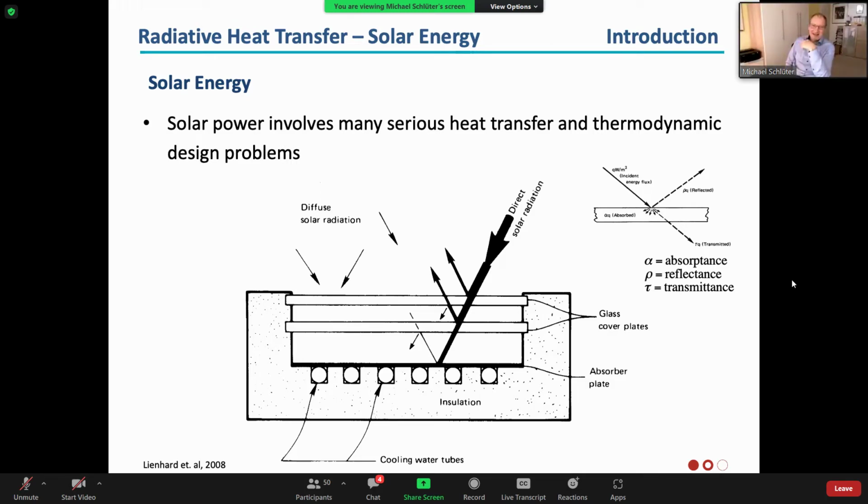You remember sunlight is reaching our Earth because the radiation works very well in vacuum. In space we have vacuum as well, so the radiation is not hindered by a vacuum, but the heat loss by convection is of course minimized by the vacuum, because if you have a vacuum, there's no fluid inside that can convect, that can transfer heat by mass transfer. Yes, right. Now I understood.